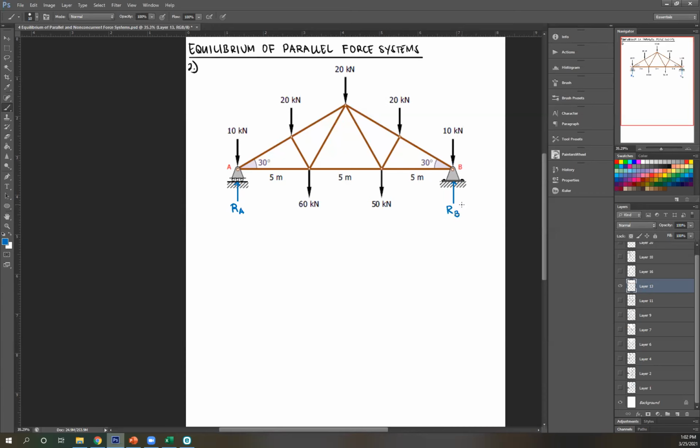So it can counter that. Now this can have a horizontal force, but that's only going to happen if we have horizontal or diagonal forces, okay? This system doesn't have any. So reaction here, horizontal, is just 0. So we don't have to include that anymore.